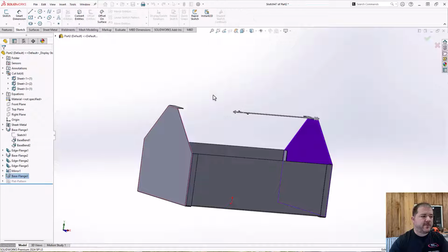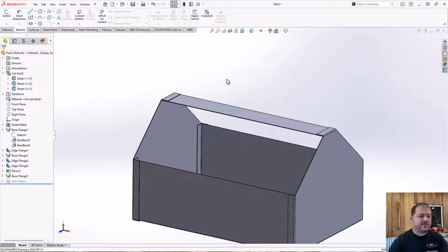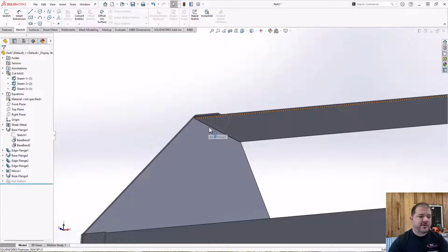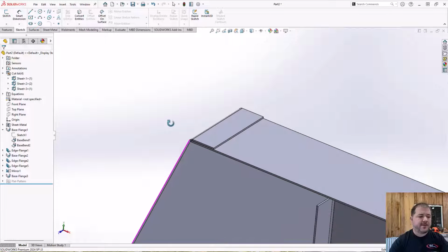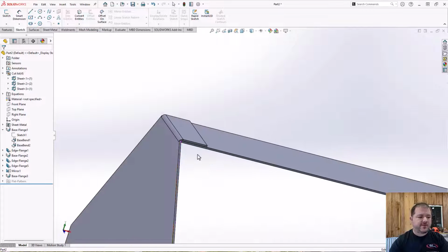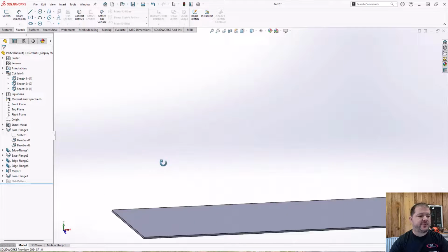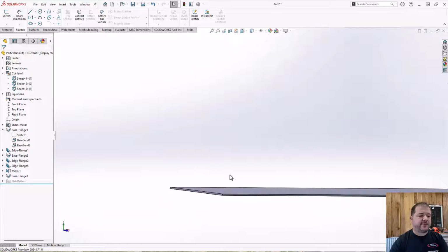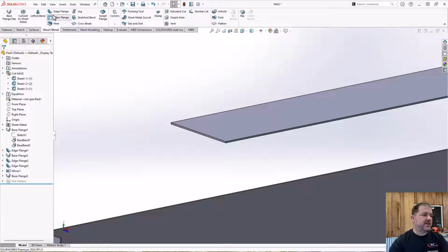All right, there we go. Last couple flanges we need to do on this one. Let's go ahead and add a flange down here so that I can stiffen this corner. Now this one, it might get a little bit difficult to see where we're working, so I'm going to hit the Tab key. Tab on your keyboard very quickly hides a part or a body in a multi-body part so that I can come in here and add my edge flange.